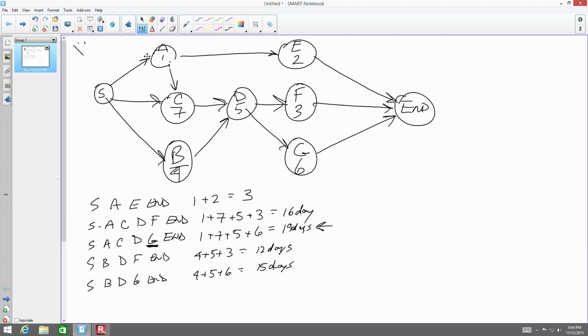Obtaining bid documents, that's definitely what you would be doing. You're getting those documents so you know what you've got to bid on, right? You would be securing subcontractor material quotations because that's the only way you can bid jobs. How much is that aggregate going to cost? How much is that truck going to cost? How much is that labor going to cost? So you would be doing that. And you would be delivering a competitive or a negotiated proposal to get the work done.